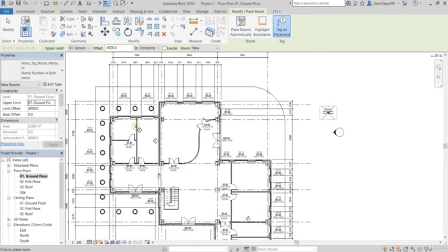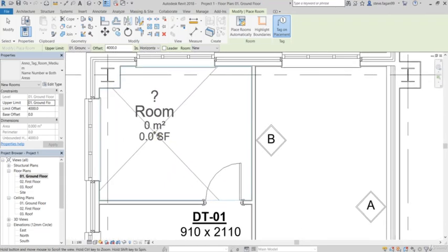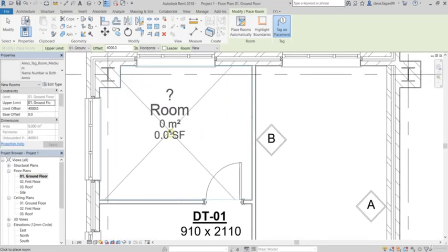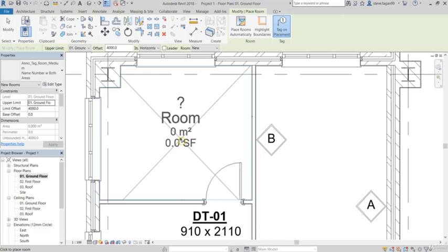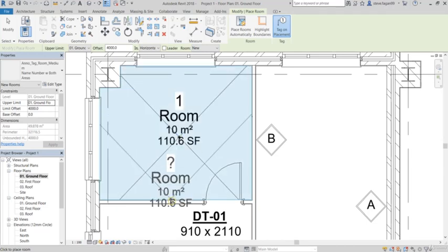So to get started, if we come over to the top left-hand corner of room, you can see when I hover inside that bounded room, I'm able to place the room itself. So you can see that that blue line is hitting each one of those partitions and the external wall, as well as going around the architectural column. So I'll click to place.